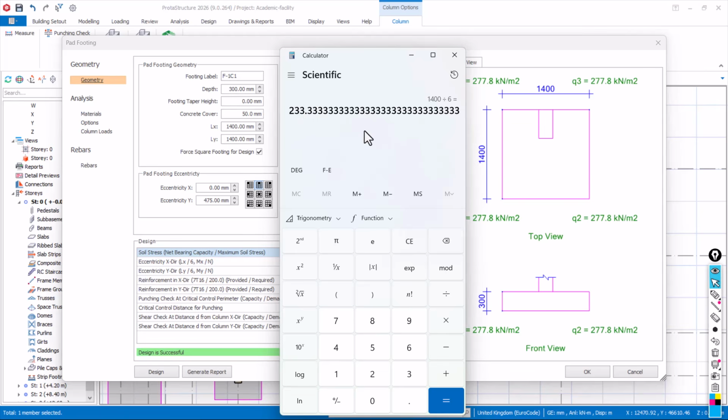Okay, so what does this mean? What it means is that part of this footing is in tension. Part of this footing now is in tension. Most things that will come to your mind: if it's in tension, why not just provide a double reinforcement, that's a top bar? Now, in the case of combined footing, top reinforcement is always there to counter the tension force. But in the case of an eccentric footing, providing only top reinforcement cannot counter the issue, because the part of the footing being in tension is not the only failure, or not the only warning that you are experiencing.